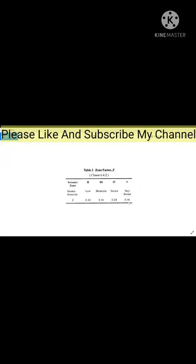So this is your zone factor, which is given in IS code table number 2, clause 6.4.2. The seismic intensity, nothing but your Z, is considered based upon the intensity: low, moderate, severe, very severe.